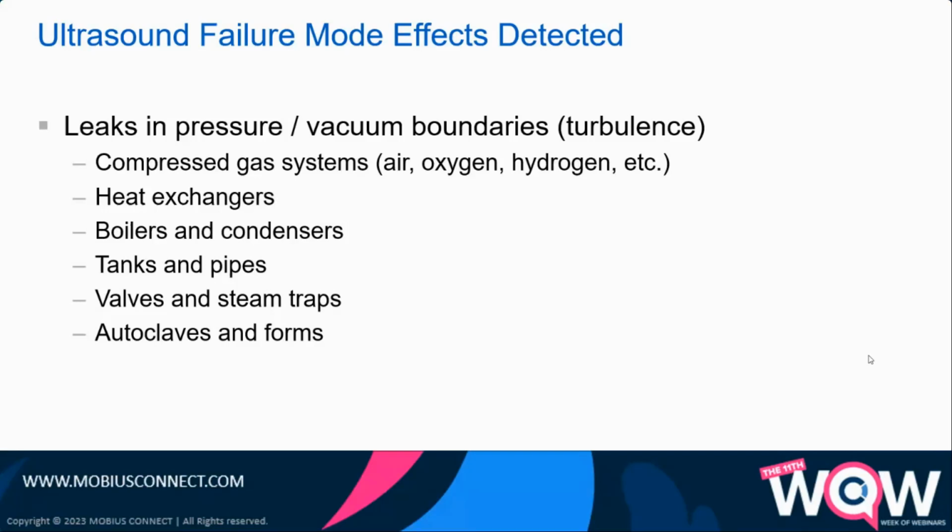So the other key thing here is that using ultrasonic detection for steam and air leaks can prove to be very beneficial for any organization. Generally, all plants have leaks. I've been in plants where their leaks are so abundant that sometimes you can't hear, right? That's the pretty obvious stuff. But organizations that I've seen that effectively implement ultrasound can identify leaks throughout the entire plant. And if they're acting on these, it can contribute to significant cost savings, and for that matter, even capacity increases in the plant. I've seen organizations actually eliminate air compressors, right, by correcting air leaks as well.